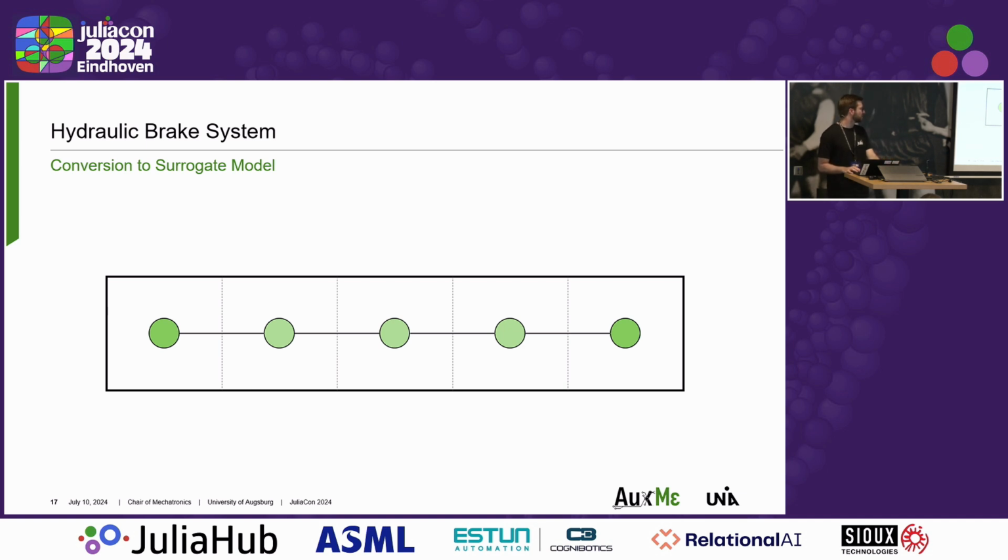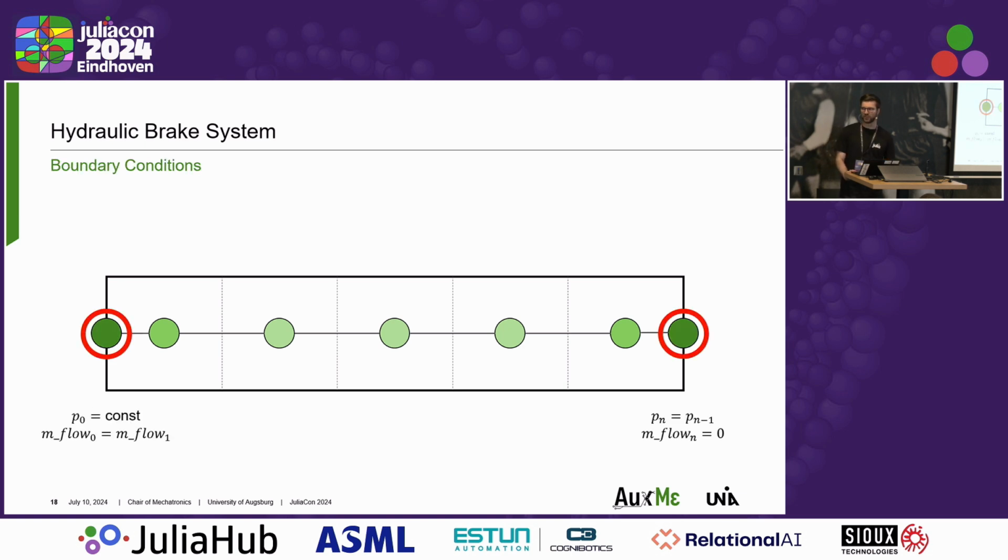One slight adjustment that we made, when I previously mentioned the boundary conditions, to help our network a bit, is that we can take advantage of the MeshGraphNet structure and try to enforce some boundary conditions in our system. So you can see on the left where the input of our system is, where the pressure wave is initiated, we have the pressure as a constant input because that is what we tell our system the input is.